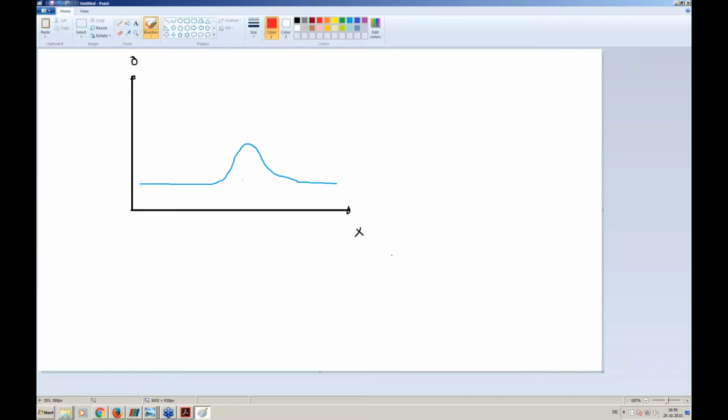And then if we would start to mesh, for example, with the coarse mesh, and we would put nodes here, then this peak would be ignored. So then we would have this kind of result from a simulation. But if we would put here 2 additional nodes, the result will become much better.